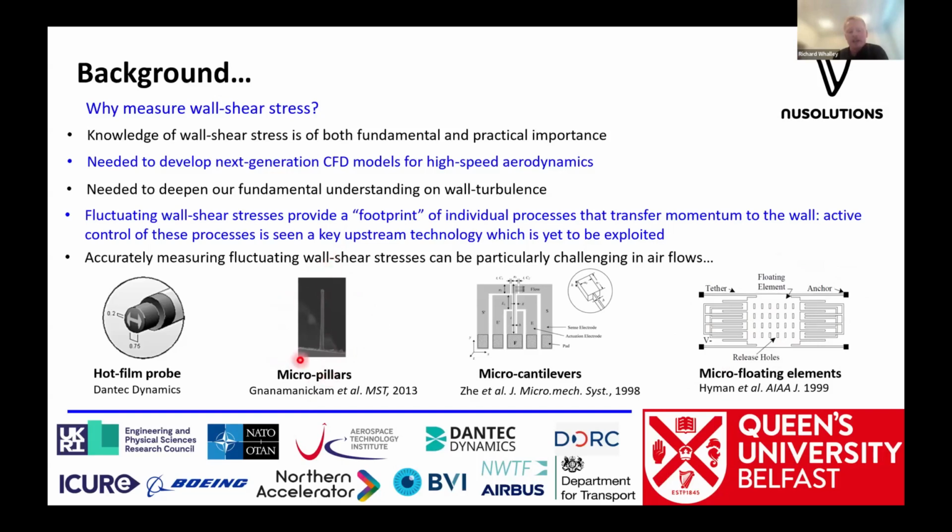However, there's some constraints. And if you try to use these in airflows, for this to be valid, this entire structure here would have to lie within something called the viscous sublayer within the turbulent flow. So very, very close to that wall on that video that you just saw. To put it in context, if you're in a wind tunnel, I'd say a modest 10, 15 meters per second, the height of the structure would have to be around 100 microns or less. And then if you scale that up to an aircraft, this would have to be more like 1 to 10 microns. And it's very difficult to find a structure which has the compliance to move around at that sort of time scale and that sort of length scale as well. So very problematic to scale these things up.